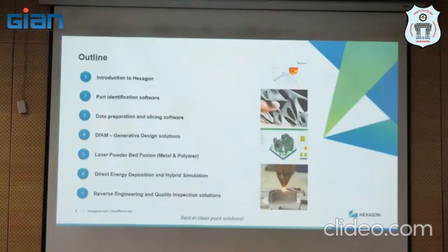So as I said before we jump in, there is something called part identification. It is not that every part can be replaced with 3D printing technology. So we have to identify the part which is more realistic for 3D printing. Otherwise, my whole exercise, my whole effort will go wrong. In fact, we have developed one software for that, where we upload the component and define this is my component and material.